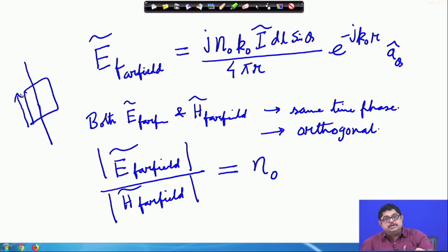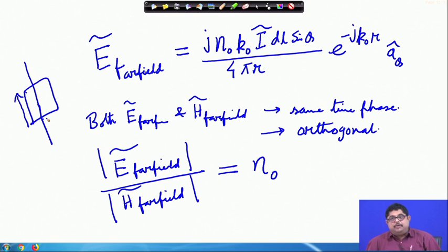There is an accumulation of charge here, and an opposite accumulation of charge here. At this instant, if this is plus, this is negative; next cycle this is minus q, this is plus q, and so on. So, there is a dipole formed here. In our current element also, due to this finite discontinuity, a dipole is formed, and that contributes here, but its effect does not go far, it is only near. So, this is the origin of this dipole terminology.